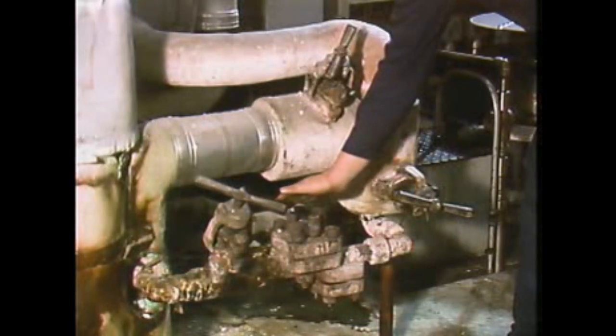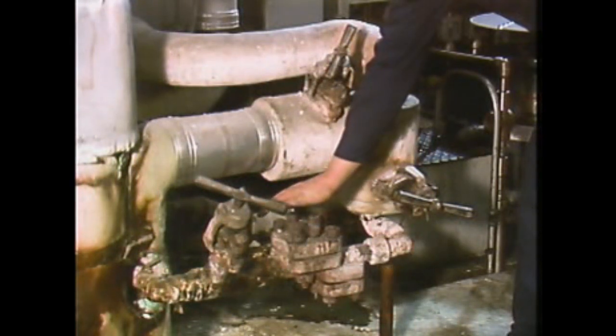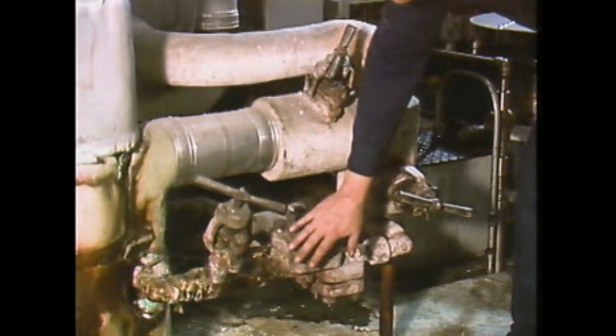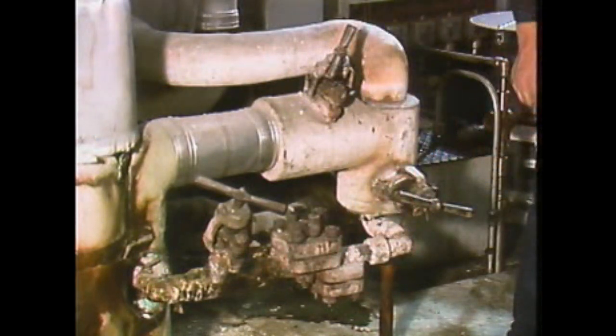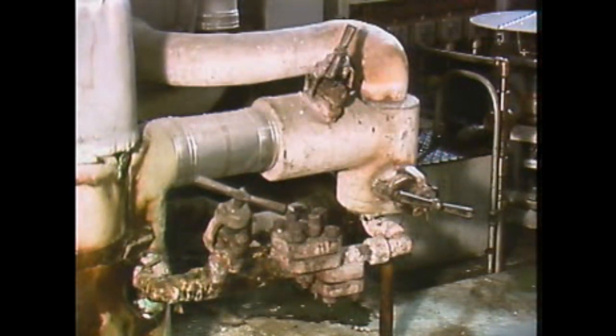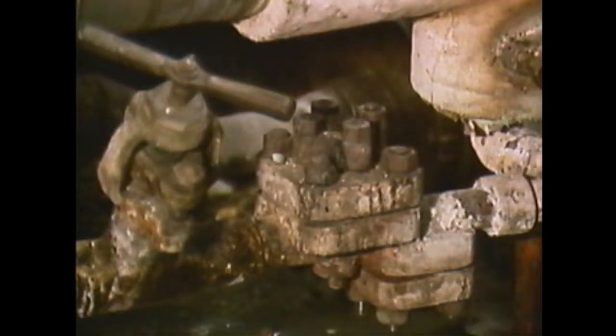It's important for you to be familiar with the temperatures of steam traps when they're operating normally. Remember that steam piping can be very hot, so you must be extremely careful when you touch any part of a steam system. If a steam trap feels too hot, the trap may have failed open, and steam may be passing directly through the trap. On the other hand, if the trap feels too cool, the trap or its piping may be clogged.